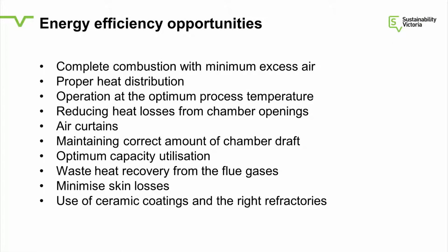So what are the energy opportunities in direct processes? Again, complete combustion with minimum excess air. In heat treatment furnaces and ovens, it's very important to have proper heat distribution into the process. You have to operate at the right temperature. Some people operate their processes at a much higher temperature than they need to, and that can waste a lot of energy because you're heating the air to a much higher temperature than you need to.